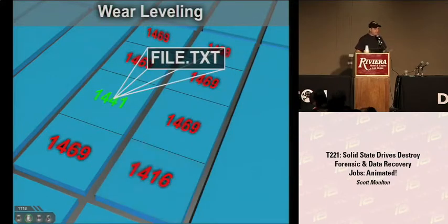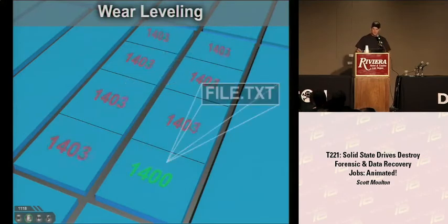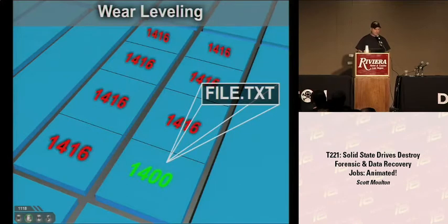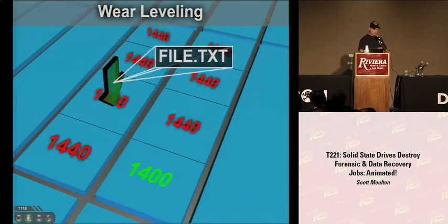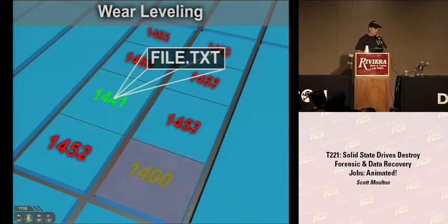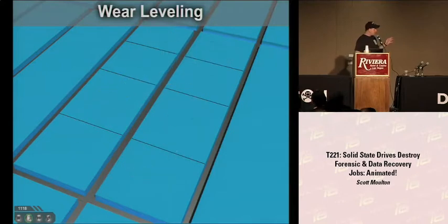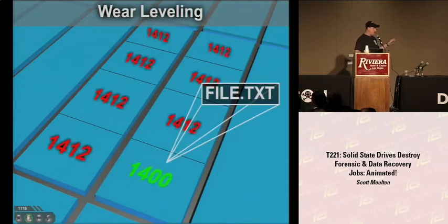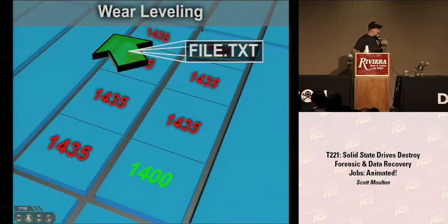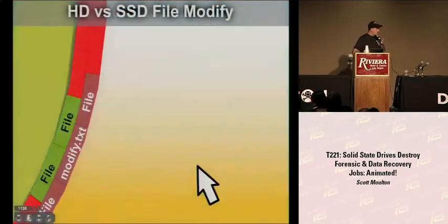So if you unplug the drive or you power it off, when you power it back on, it looks at the garbage collection routine, and it starts right back where it left off, even though there may be something new added to the garbage collection routine while you've booted and run it. It's not going to happen in that order. It's going to happen in the order of the queue and how it stored it. So that's physically the function of wear leveling, to try to keep the chip from being destroyed in the process of using it. So this is what it looks like on a hard drive.